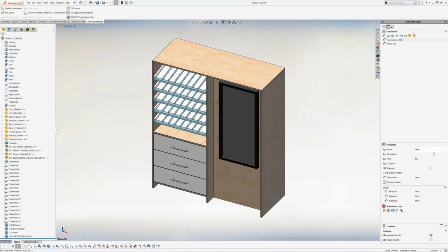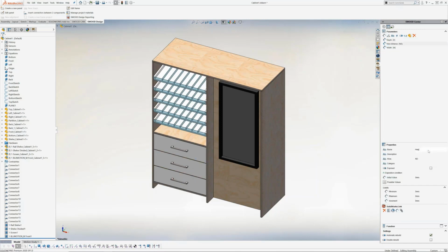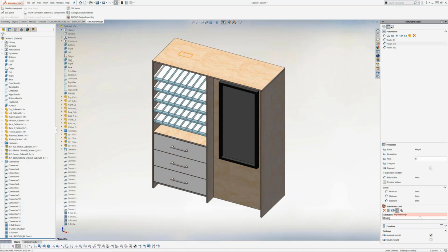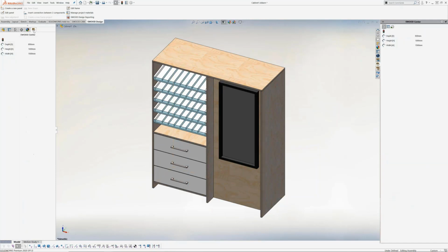And of course, the possibility like that to customize the properties with the names, the alias, and of course the link to the SOLIDWORKS definition, the SOLIDWORKS link to be able to drive everything. So you can see now when we update our model, we can have on the left side all the parameters we have exposed to be able to drive everything at once.